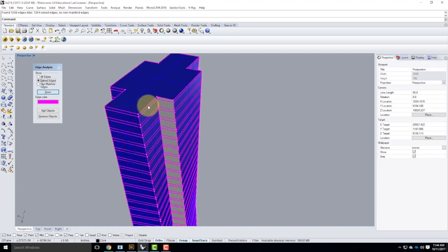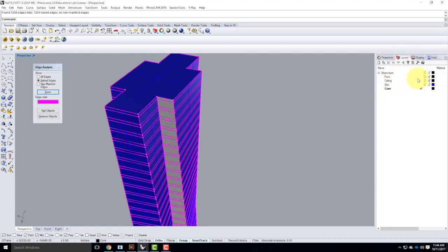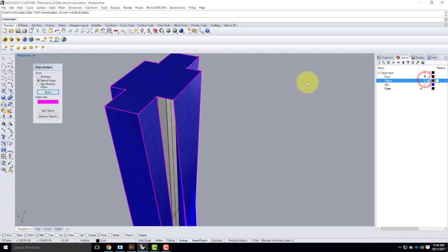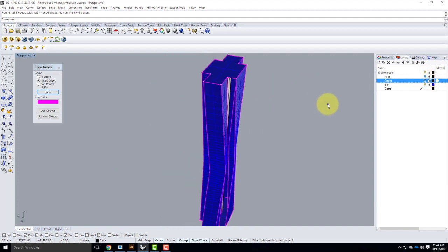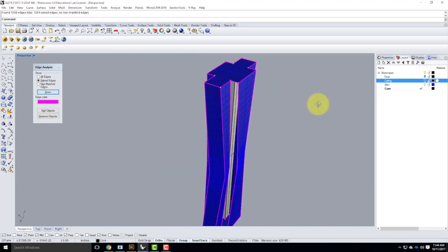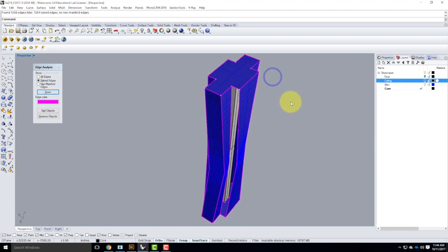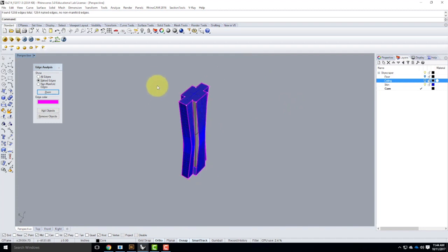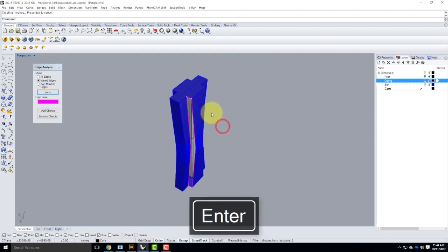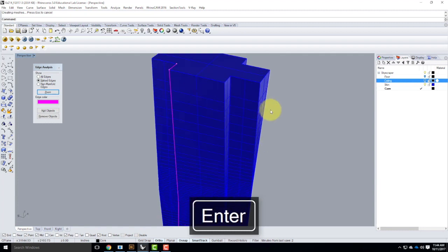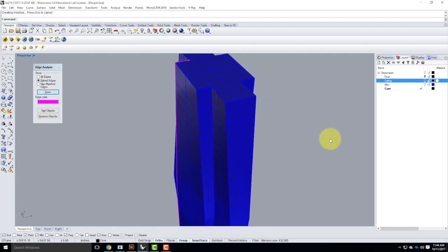So in this instance, I told you it wasn't going to like all of the floors. So the floors are a problem. Let me go ahead and get rid of the floors for right now. I'll just turn off the floors and the ceiling. Notice that all of those go away nicely. Okay, so that's good. We got rid of a bunch of problems, but we still have problems on all these sides. Well, if I took all of these sides and said, let's join them together, and we looked at it, okay, that solved all of these sides because they're now joined closed surfaces.